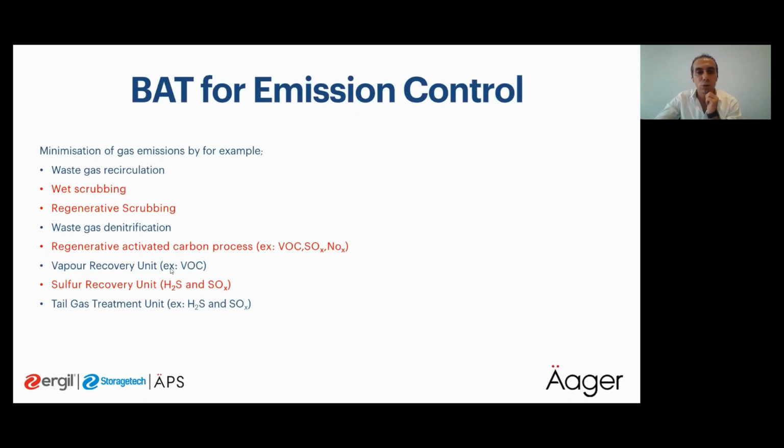So if you use a wet scrubber in the chemical company, maybe in the printing company you should change the system to something like an absorber, activated carbon, or vapor recovery unit. It depends. It changes with your requirement, and it depends on the pollutant flow rates and concentration.